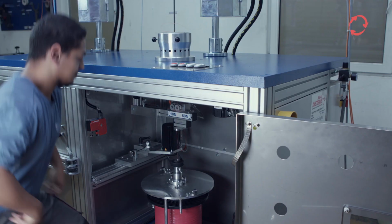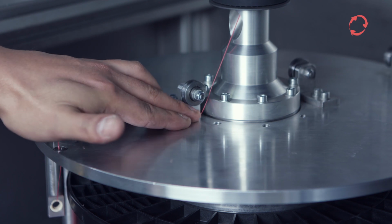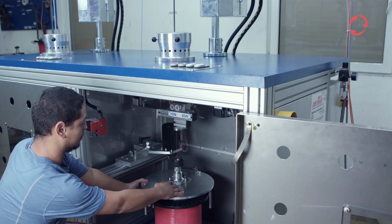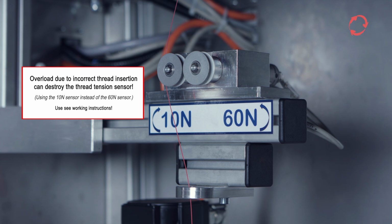After knotting, rotate the coil back so that the thread is under tension and press the protruding thread under the second roll of the wrapping plate. Then place the thread on the respective thread tension sensor. Which thread tension sensor is used depends on the dimension of the monofilament and the size of the spiral.